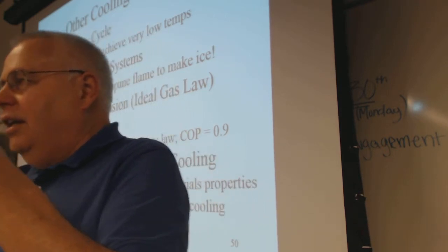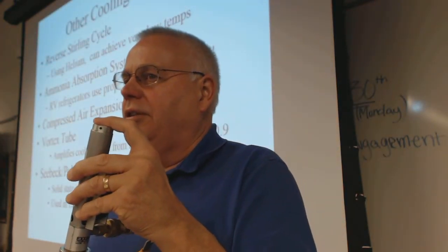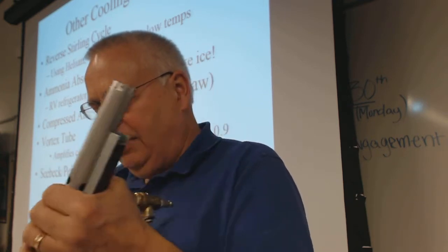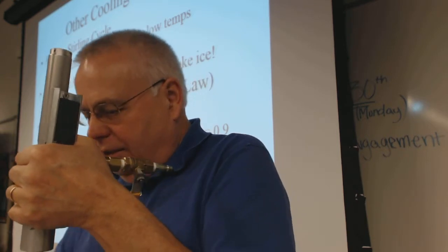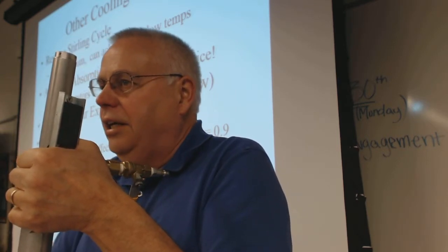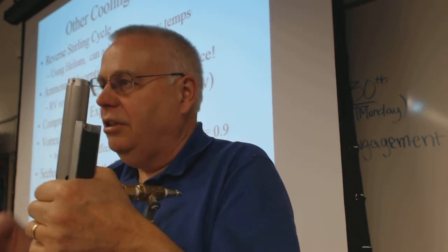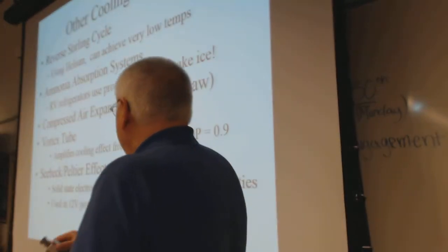So they'll use this. If you're cutting plastics, you don't want to get a bunch of cooling fluid and oils trapped in your plastic, smushed around. You can have one of these mounted to the machine tool, and a cold air blast that's just in that area right before the tool that pre-chills the plastic so it doesn't cut like bubble gum. It cuts nice and sharp.